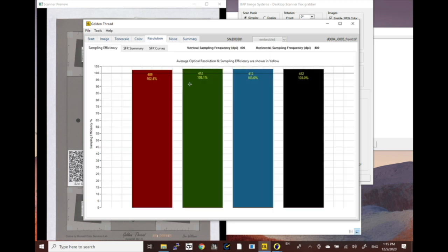Our resolution, that's something that we were talking about, and it's very interesting. It's 400 dpi. This is my sampling frequency. The sampling is normally what the RFPs specify, or when you open your Explorer, you'll see in properties that it's 400 dpi. But that 400 dpi doesn't really determine if it's a good quality image or not. It just tells you that there are 400 points in 1 inch. Maybe you are completely out of focus, or maybe your lens has a lot of dust, and many things can influence it, or there's a lot of compression.